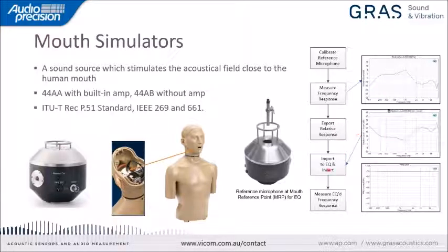Then we import it back to the software, and when we do that, we invert it and we use it as an EQ for the output channel that is used with the mouth simulator. And therefore, when we perform the test again, we can see that the final response is a completely flat frequency response. And this is when we are ready for measuring after equalizing the mouth simulator.